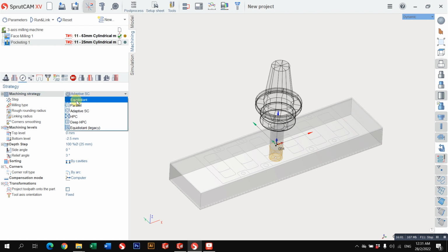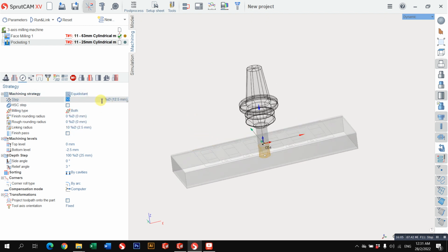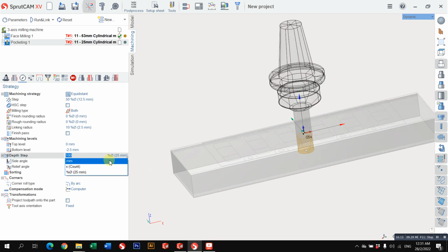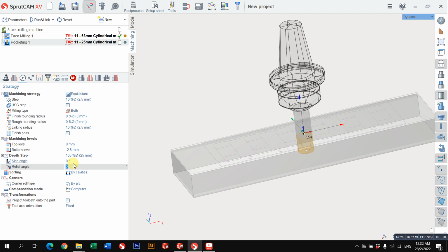Let's say I just want a straight away cut, 100% cut, so I can use a smaller step over, 2 mm step over, or using percentage, 10% step over, so 2.5. Okay, no relief. Okay, no routing extra stop. Okay, then we can just try running.